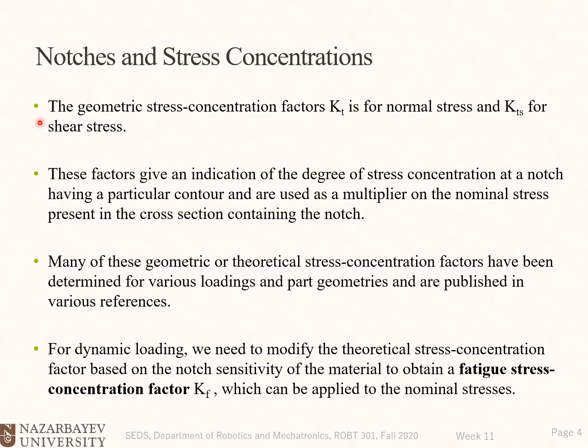The geometric stress concentration factor Kt is for normal stress and Kts for shear stress. But both of these, Kt and Kts, are for static loads.